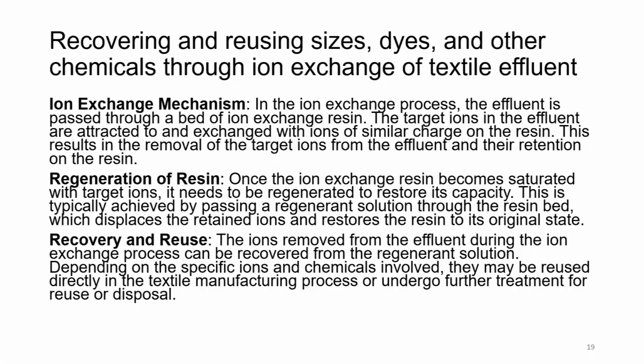Recovery and reuse. The ions removed from the effluent during the ion exchange process can be recovered from the regenerant solution. Depending on the specific ions and chemicals involved, they may be reused directly in the textile manufacturing process or undergo further treatment for reuse or disposal.